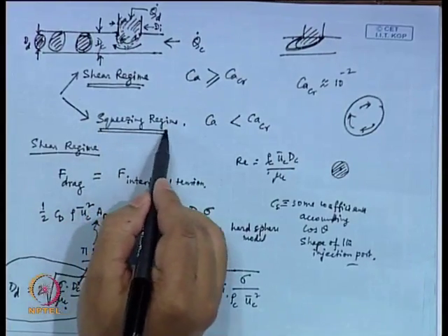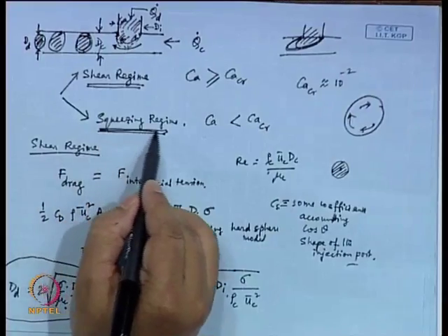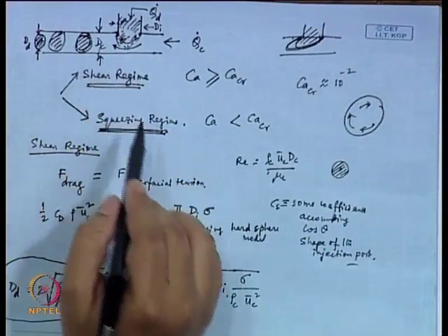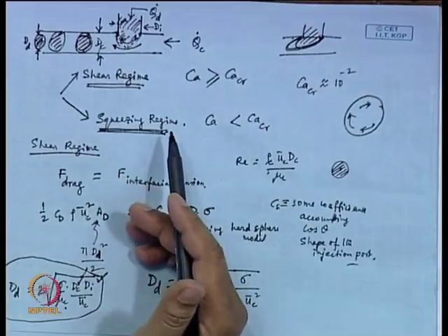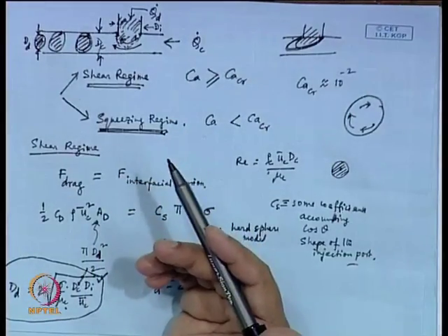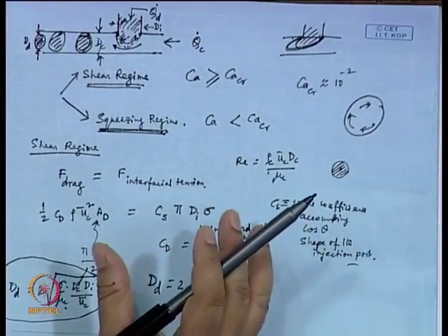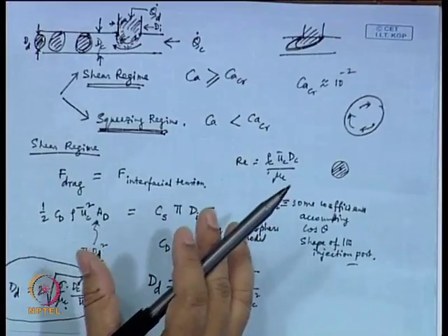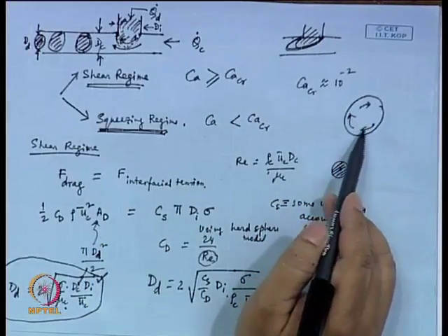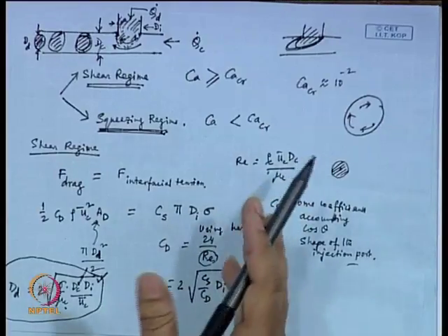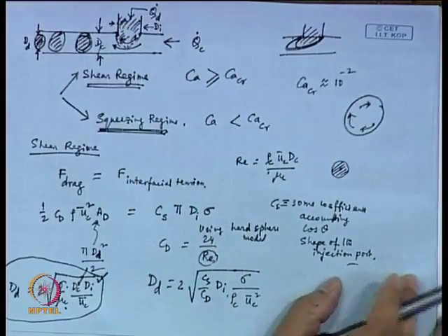So, this would again be a T joint, same thing, only the shear would be absent. So, if you ask me how do I know that when capillary number is greater than CSCR, it is the shear mode that is responsible for the breaking up, researchers have already observed that there are remnants of that shear present at the downstream.